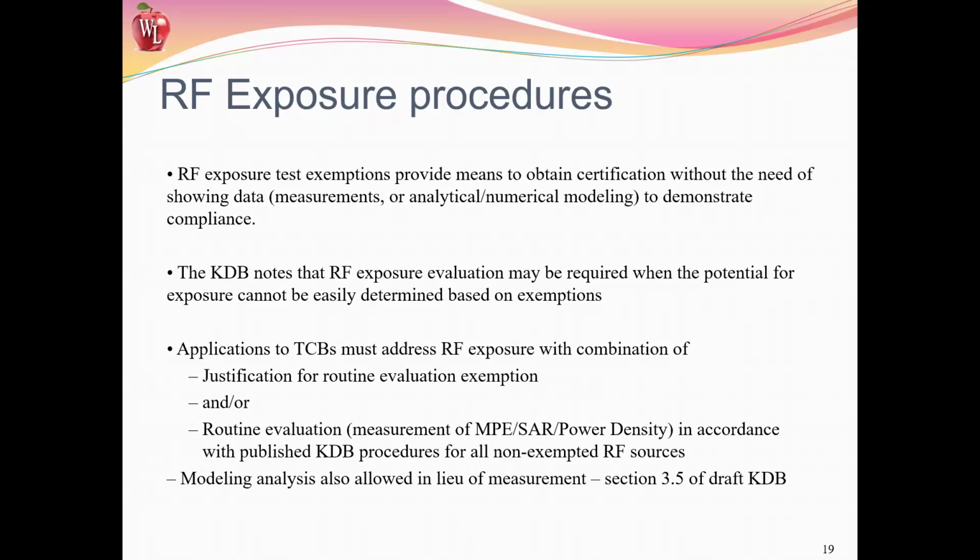Applications, when you send them to the TCB, have to address RF exposure. All transmitters have to address RF exposure. If you're looking for an exemption, you have to have justification for that exemption, or you need to do routine evaluation: the SAR tests, the MPEs, power density, APD, IPD, in accordance with the KDB for all non-exempt sources.